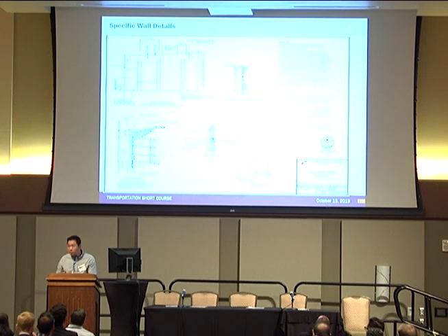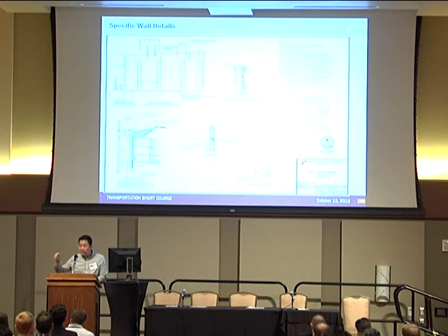The inspector or the project manager should carefully review and go through all the plan notes in the soil nail layout. Typically, a soil nail layout calls out the maximum amount of time that you can leave a nail cut. Once you cut, you need to punch the nail, grout, and shoot the shotcrete the next day. The punching, grouting, shotcreting, including putting on the bearing plate and bolting, is one day, and cutting is another day.